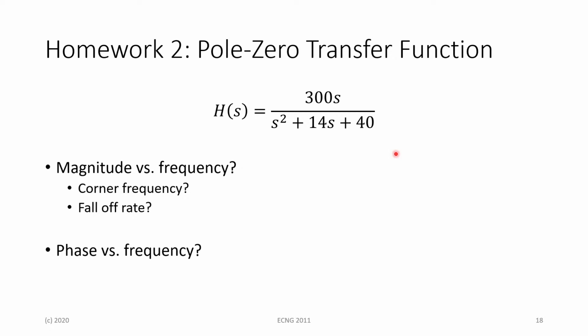So for the magnitude plot, and I'm repeating this, make sure that you write down on the magnitude plot the resultant gradients for each one of the lines for the resultant plot. And for the phase plot, do not forget to write the angle equation because that also contributes towards marks in the question itself.